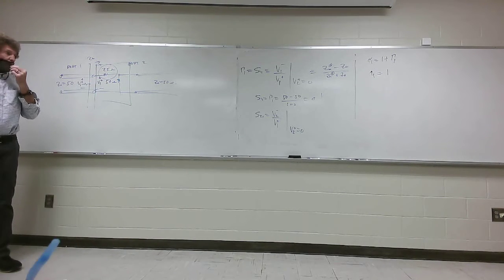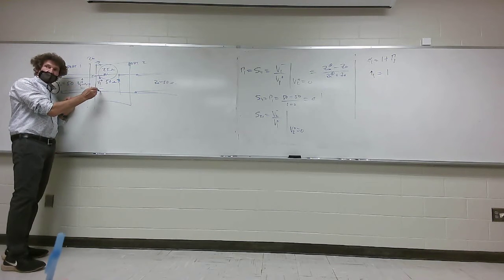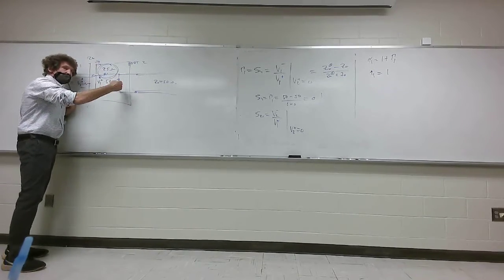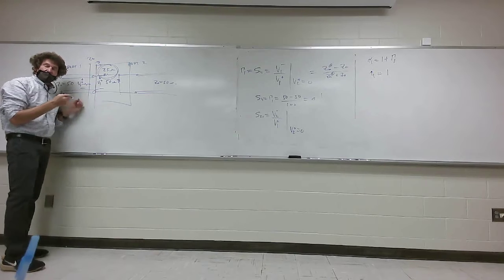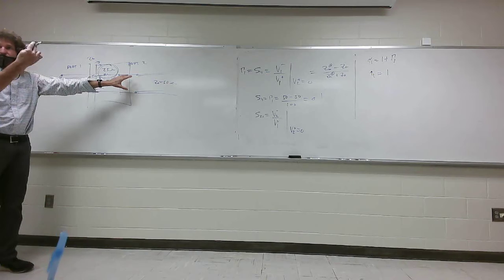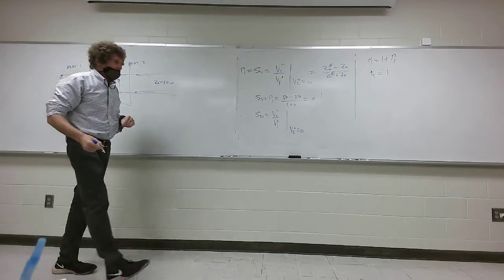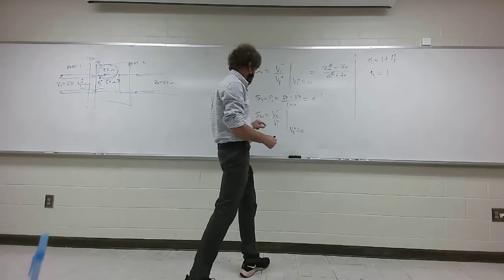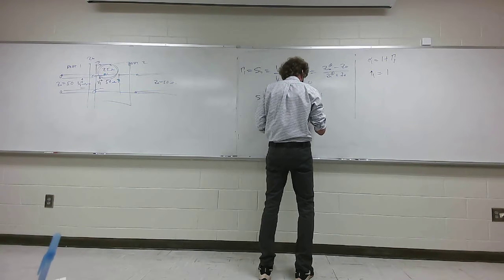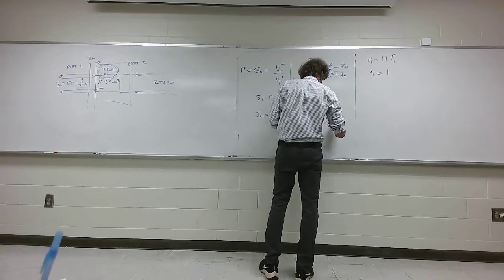All right, now, what happens when that voltage gets here? Just take a look. I have a series resistance of 25 ohms, and isn't this really equivalent to 25? How many see that I would have exactly what? It would be 25 over 25 plus 25, or 50. 25 over 50 times V1 plus. So I could say right here that V2 minus is going to be 1/2 V1 plus over V1 plus, or it's simply 1/2. Y'all follow me on that?